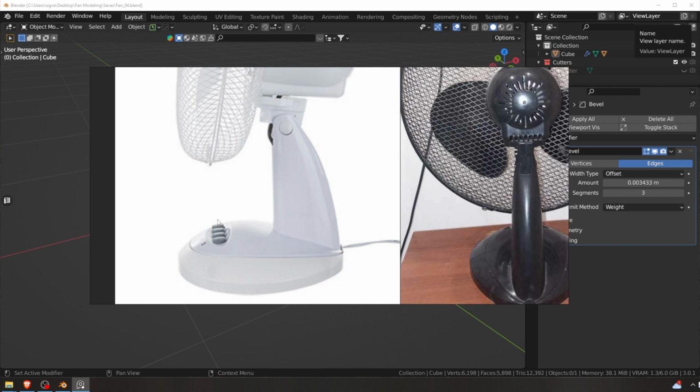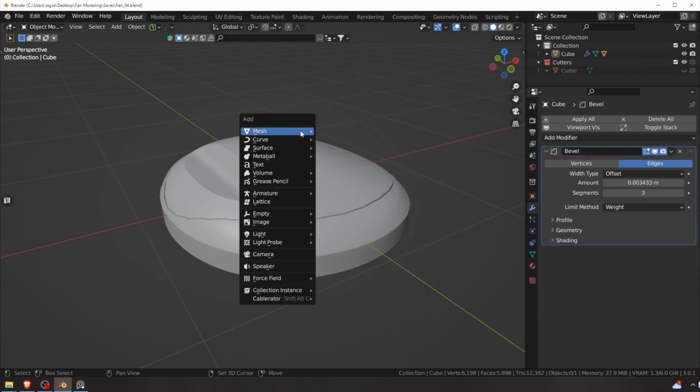Usually it's very hard to get away with HardOps and Boxcutter only when you have curvature in two sides like that. If you have curvature on one side like this, then it's just bevels. It's not that difficult. And right here, you would say, oh, that's two directions, but it's still a corner. You can get away with corners like that because you bevel one side. Let's say we bevel these sides and then the top part. So let's go. Let's get into it.